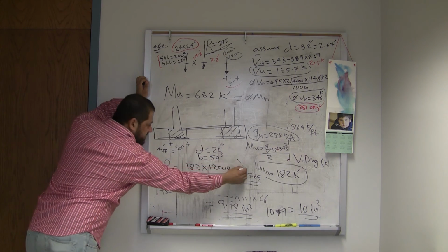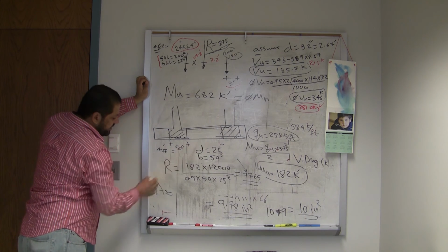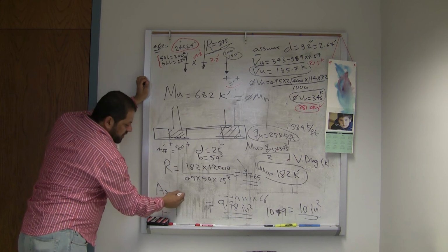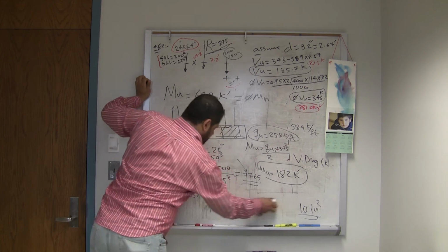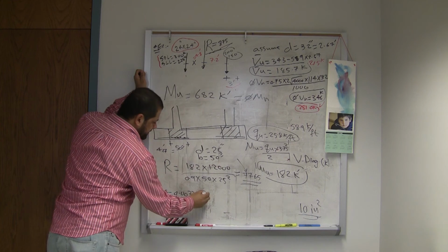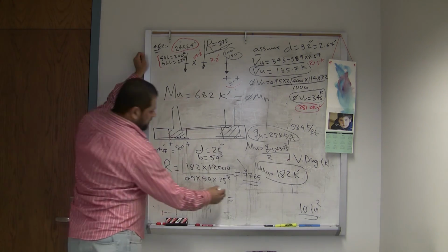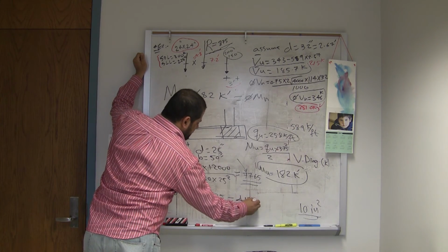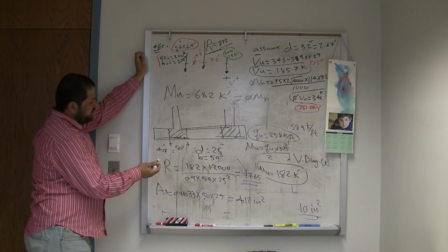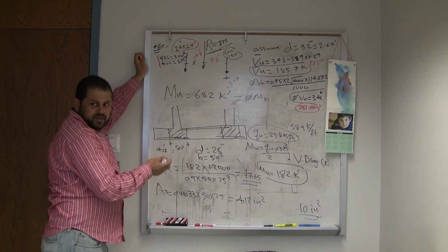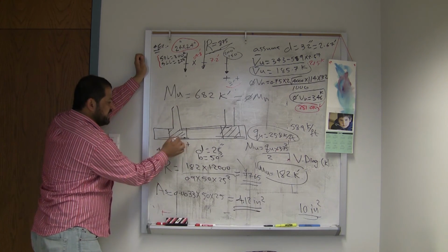If you go to the design aids, this will give you rho less than rho minimum, because we checked it for something higher than that. So AS will be rho minimum 0.0033 times 50 times 25, equal 4.12 inches squared. You can use, let's say, 5 number 8. I'm not sure if they're going to do it or not, or 6 number 8. Maybe they can do it. But you pick steel to provide you something more than that, and this will be in this area here.